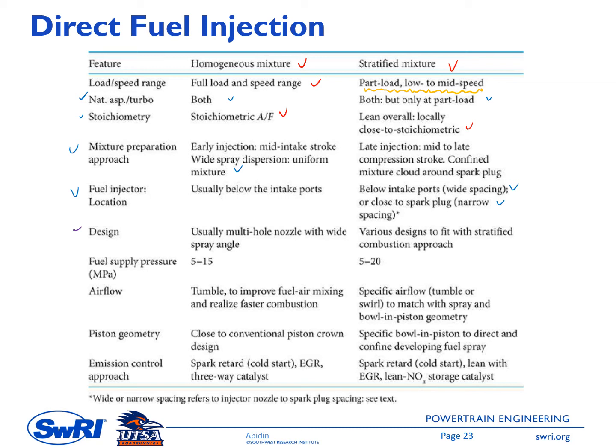And then regarding the fuel injection pressure, for the homogeneous mixture, we typically have an injection pressure between 5 to 15 megapascal, or 50 to 150 bar. For the stratified mixture, it is similar, with a slightly higher upper limit of 200 bar.